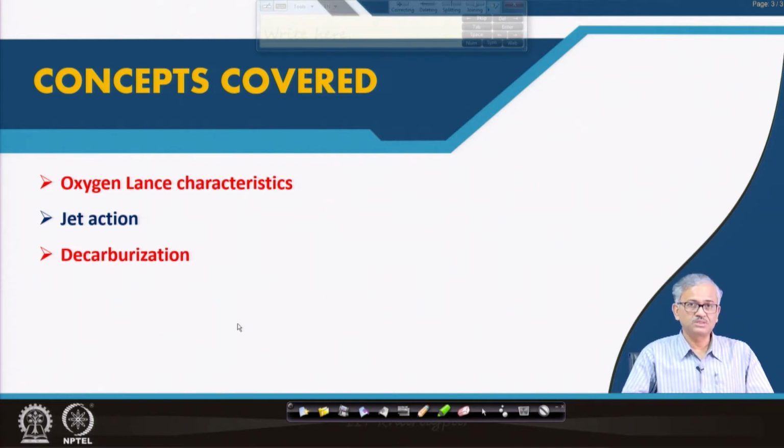So decarburization has a very important role in LD steel making, because it has to continue to the end such that you can keep the foam and emulsion stabilized to the end of the process, because only in the emulsion do you have a tremendous slag metal interfacial area, where kinetics is fast because of that. So the decarburization reaction has a very special importance in LD steel making.